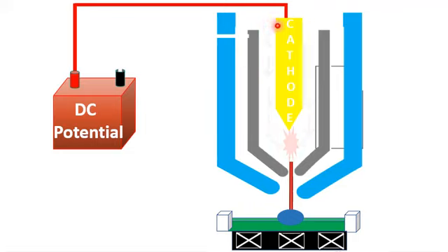The cathode and anode of the plasma arc igniter are connected with a high potential direct current source. For the cooling system, usually water cooling lines are incorporated across the plasma arc igniter system to decrease the temperature of the electrodes, and they are also used to decrease the temperature of the cathodic systems.